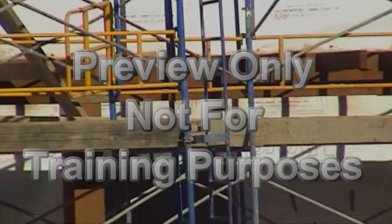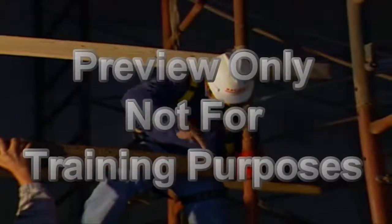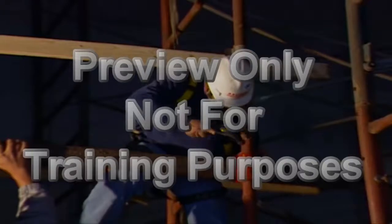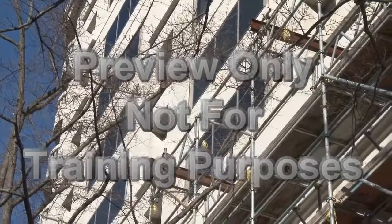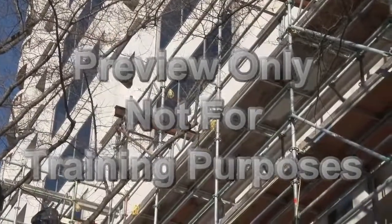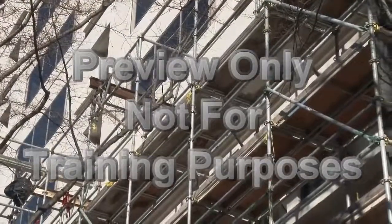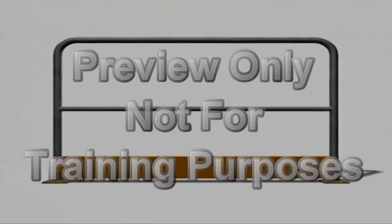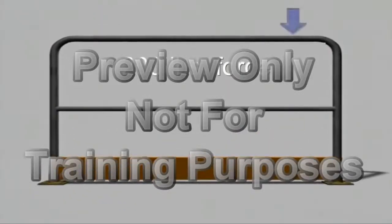Guardrail systems must be installed along all open sides and ends of platforms and must be completed before the scaffold is allowed to be used by workers other than the erection and dismantling workers. Walkways within the scaffold must have guardrail systems installed within 9.5 inches of and along at least one side of the walkway. The top rail must be able to withstand a force of at least 200 pounds applied either downward or horizontally at any point along its top edge.